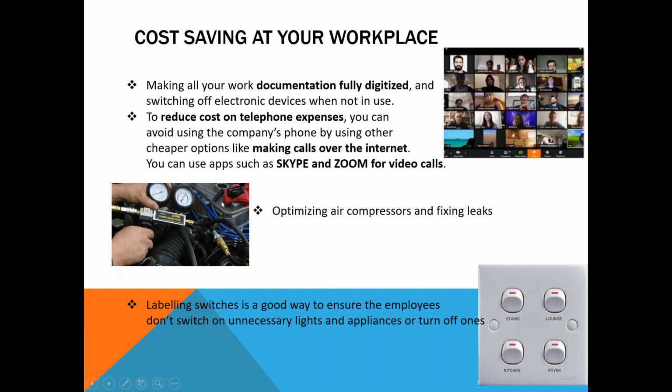I have seen in many companies, a compressor is running unnecessarily. After I checked what the on time and what the off time is, it was found that there is a lot of leakage in many spaces.